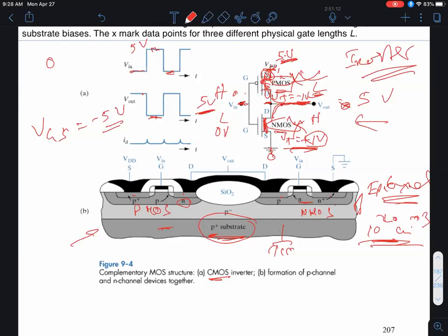I'm not going to go into the physics of that. The way you make these epitaxial thin films was discussed in section 5.1 in chapter 5. And it's also discussed in the Silicon Run video that hopefully you got a chance to look at, okay? Basically, you throw in gases containing silicon at high temperature, and you grow these planes of silicon layer by layer using the underlying substrate as a seed, okay?